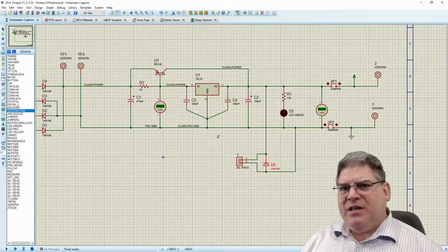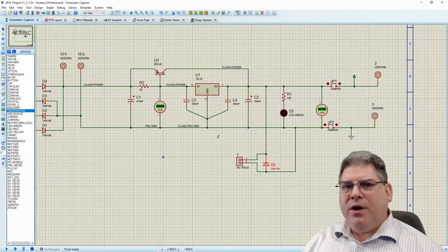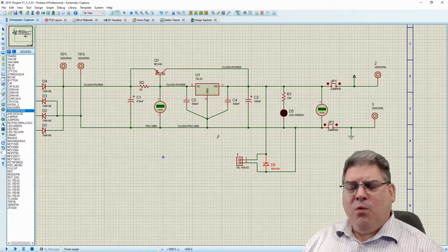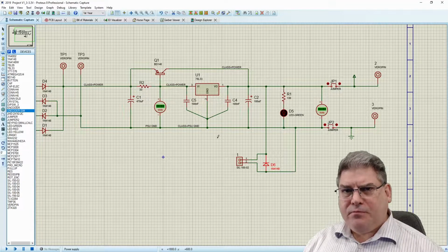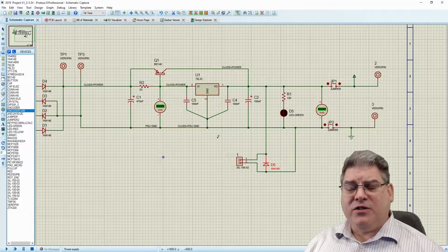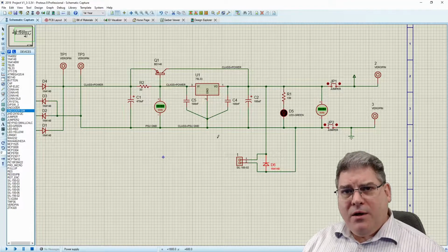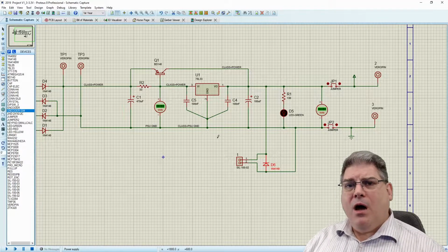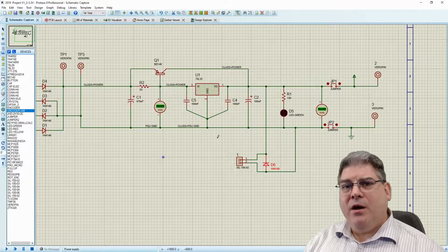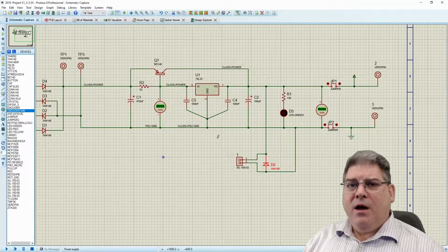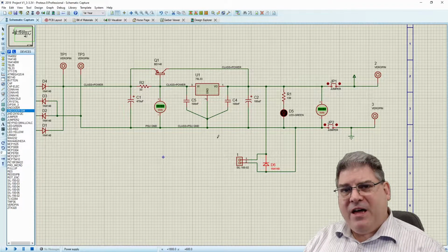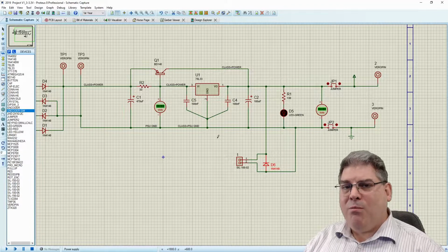Often we have circuit boards that have multiple voltages on one design. The reason we do that is because we want to have high voltage and low current running everywhere that we can across the circuit board, because power is voltage times current. If we're delivering X number of watts to a chip, it's much easier to bring in, let's argue, a 12-volt line to that chip, and then at that chip, step it down to say 1.2 volts.